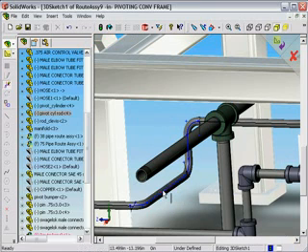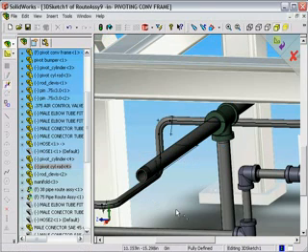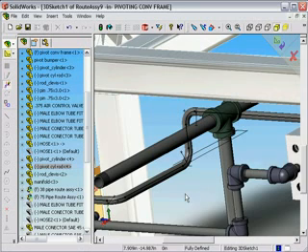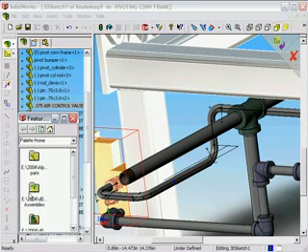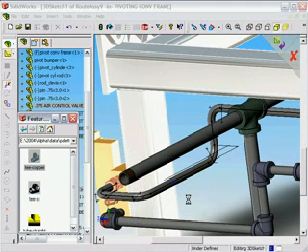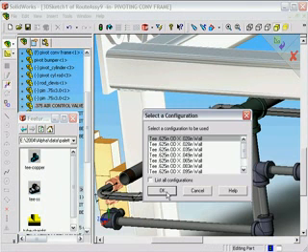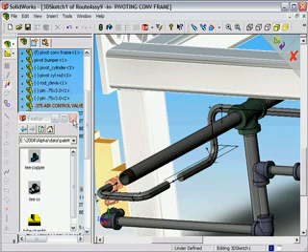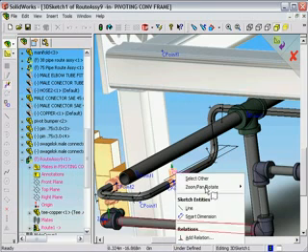The benefit of designing with SolidWorks Routing at the assembly level is capturing design intent. We're going to dimension off the edge of the frame of our assembly in order to put a hanger in later. If we want to add additional fittings, we simply split the tube. And from our SolidWorks feature palette, our library of components, we're able to drag and drop tube-specific components into our assembly. They're very easy to orient, and then only the correct list of sizes are presented to the user. Once we've added fittings, we can continue to route off in new directions.